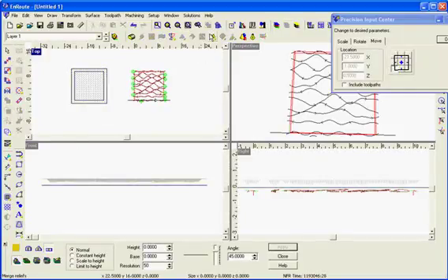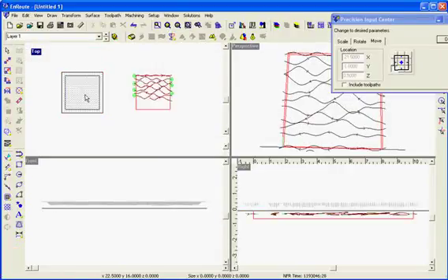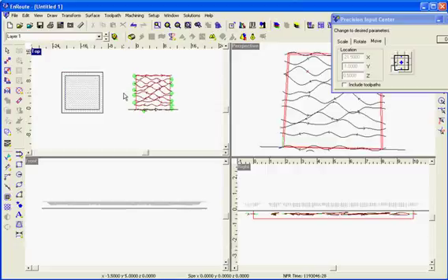I'm going to go to the Merge Reliefs button, follow the little wizard here that tells me to select the base relief, hit the forward key, the play key, select the relief I want to merge, and I'm going to add the second relief to the first one, so that way I'm trimming away the unnecessary part of this rapid texture, which would be the same thing that would happen if I then came and cut this shape out.